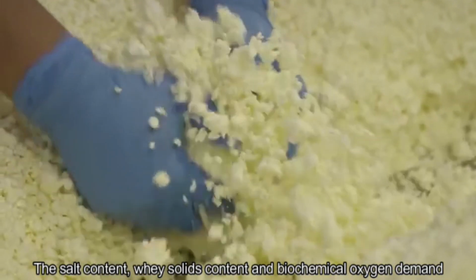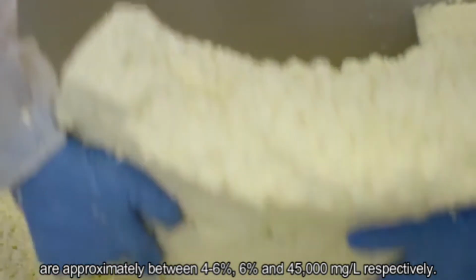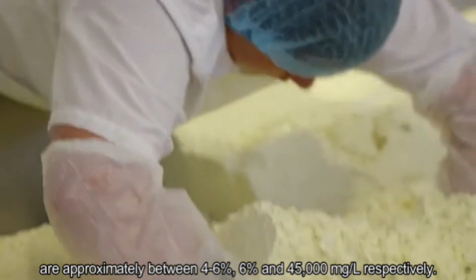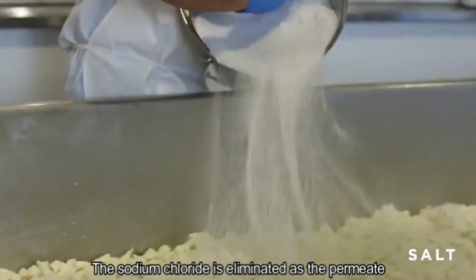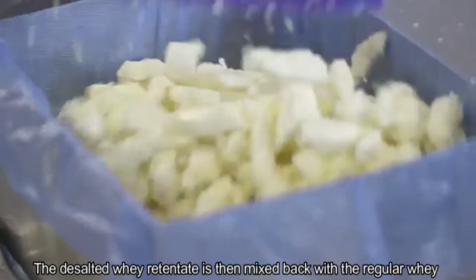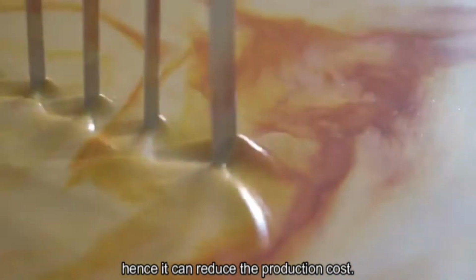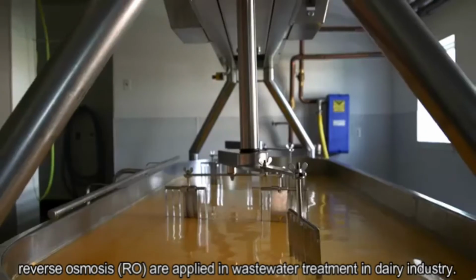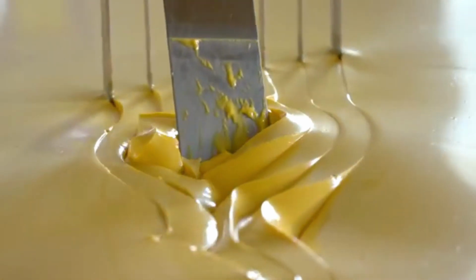The salt content, whey solids content, and biochemical oxygen demand of the salty cheese whey are approximately between 4 to 6%, 6%, and 45,000 milligrams per liter respectively. The sodium chloride is eliminated as the permeate, which is then recycled or discharged by the nanofiltration system. The desalted whey retentate is then mixed back with the regular whey, hence it can reduce the production cost. The combination of microfiltration, ultrafiltration, and reverse osmosis are also applied in wastewater treatment in dairy industry.